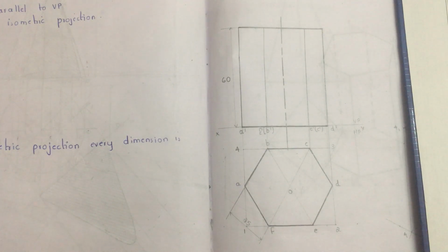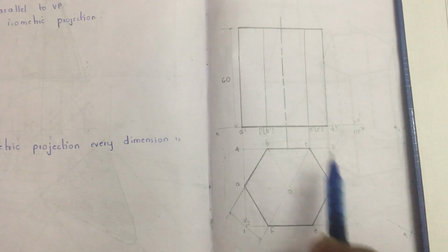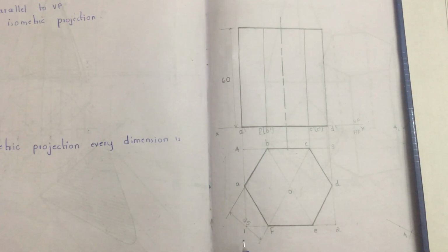So, whether it is a hexagon, a pentagon, a square, a circle, any solid, your task is to ensure that you place that solid of the top view in a rectangle, and you can name it as 1. This point should always be named as 1. Okay, which point?